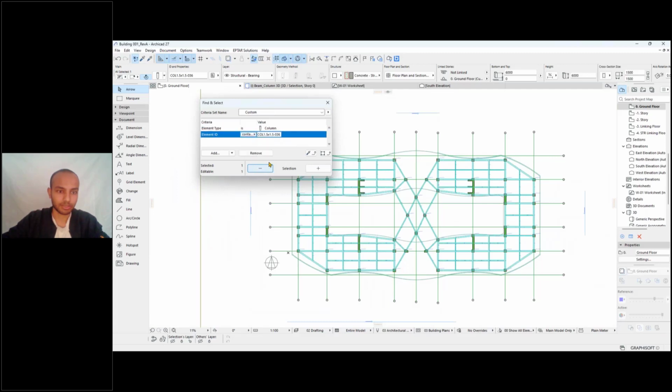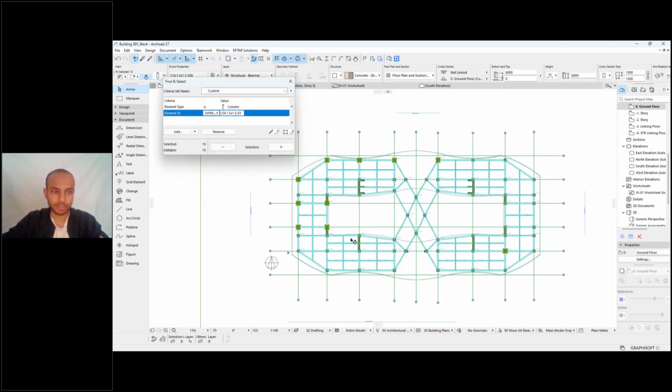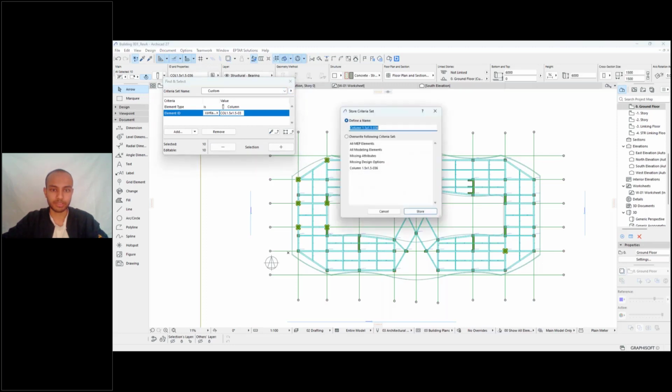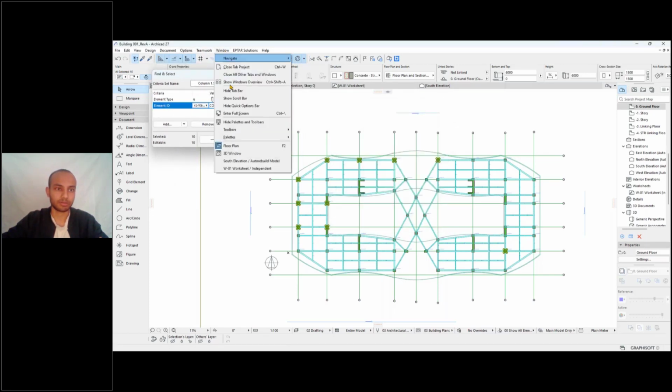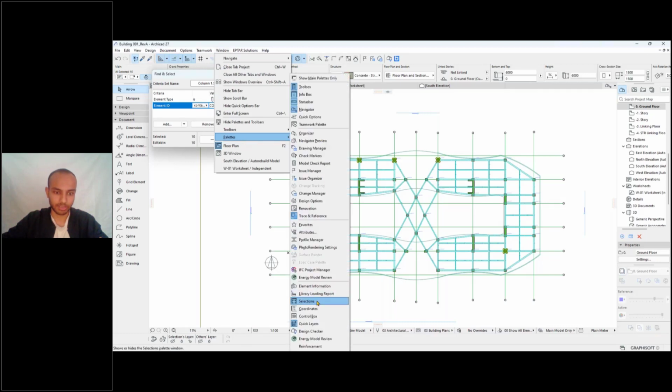And let's say I selected it over here. And let's try to select more of the elements by just doing this. It contains 3. Then okay, so at least 10. So these 10 columns, I want to revisit them, right? So I can either do store as, I'll store them as this, or I can also make use of our other palette, which is the selections.